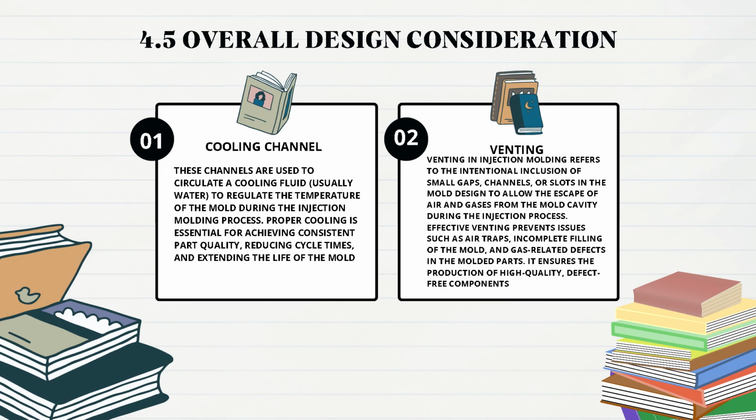Okay, next for our overall design consideration. First, cooling channel. These channels are used to circulate a cooling fluid, usually water, to regulate the temperature of the mold during the injection molding process. Proper cooling is essential for achieving consistent part quality, reducing cycle time, and extending the life of the mold.